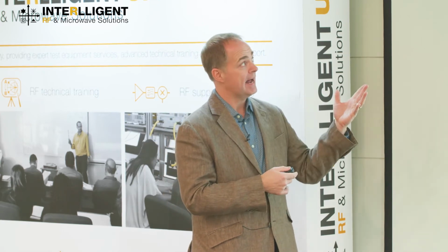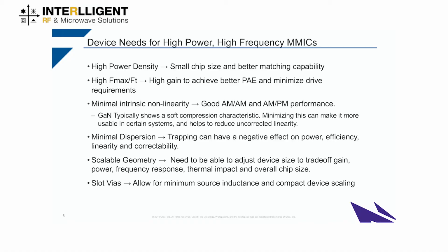We want to get high Fmax and high FT so that we can actually achieve the PAE and minimize the drive requirements, right? This is how we actually get enough gain to get sufficient PAE out of the device to make it usable in an application. We want minimal intrinsic nonlinearity, so good AM to AM and AM to PM performance.